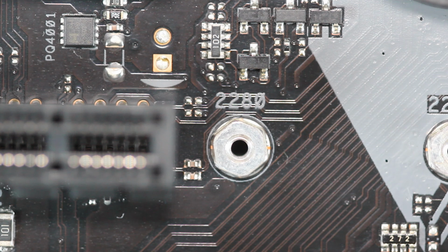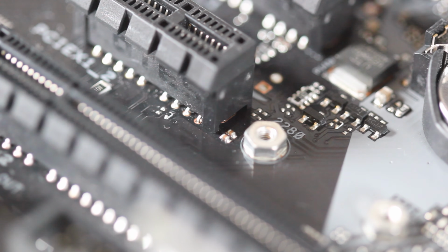The first thing I would do is locate the 2280 form factor position. If you are not sure, you can always look at the manual or use an existing M.2 SSD to measure it. Although it is possible to get M.2 SSD in other sizes, it seems the market for the moment has standardized on 2280. So it is a pretty good bet that when installing a new M.2 SSD, it will be that size. As before, I will just screw the standoff in.